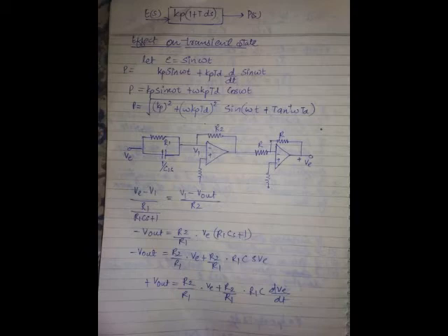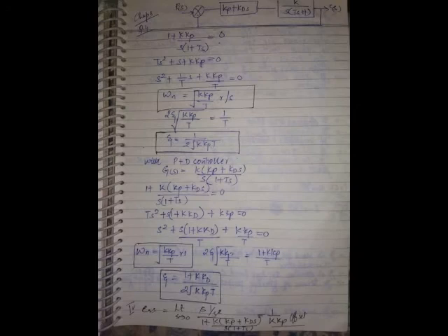P plus D controller. P plus D mode. The analytical equation is, as I said, you can write KD dE by dt. This is also correct. When you do theoretical analysis, it doesn't make any difference. You can also write directly TD here. But these are crude forms. The correct way to write the analytical expression of any composite action is Kp TD dE by dt.